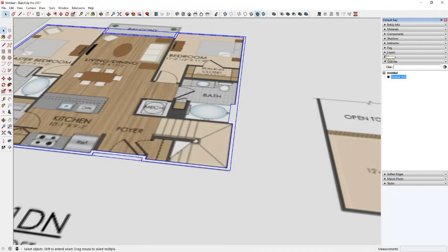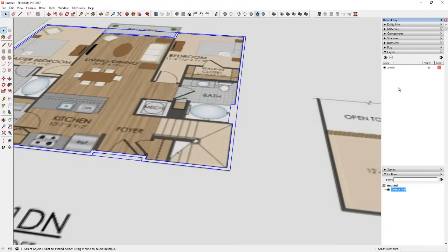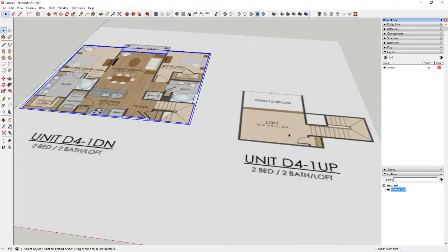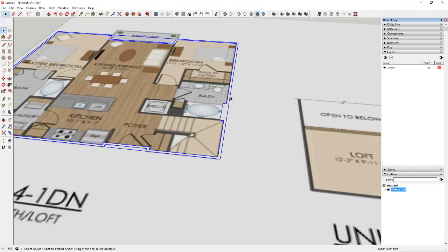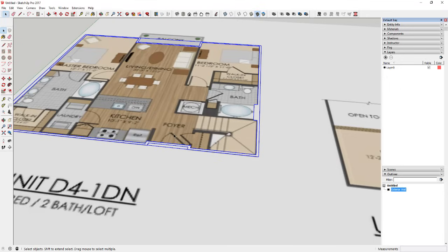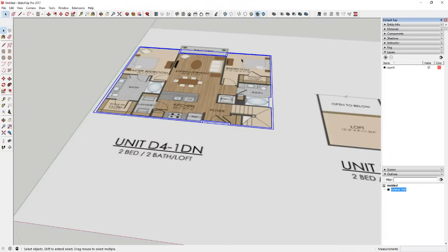In addition to naming that exterior wall, I'm also going to start organizing by layer, because you want to be able to turn things on and off, so we need to put these groups on layers as we go. There are 3 different kinds of layers we're going to talk about. There are levels, which we'll use to separate level 1 from level 2, so we can turn level 2 off. Then there are layers for more conceptual things, like door swings and other stuff that's going to make your model look good in layout when you take it to 2 dimensions. And then there are architectural items, which are the things that are actually geometry in your model.